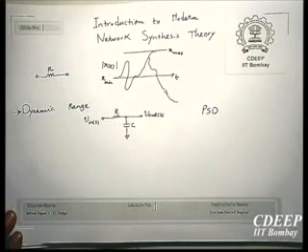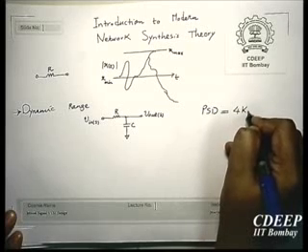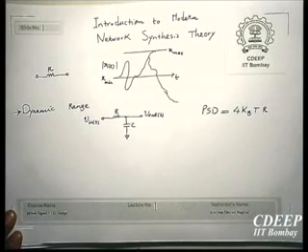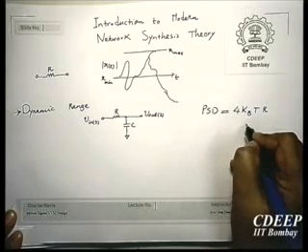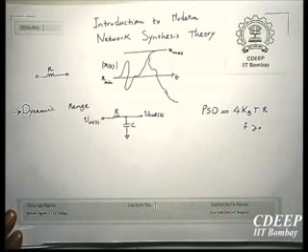You know, the power spectral density of noise in a resistor is 4kTR for frequencies above 0. If you make it 2kTR, then it is for all frequencies. This is a constant value because the power spectral density of noise is flat, which means that thermal noise is essentially white noise.